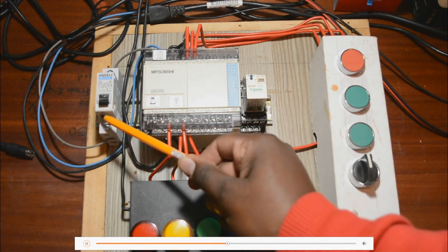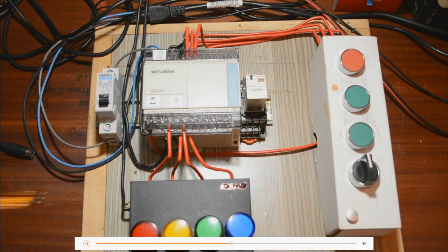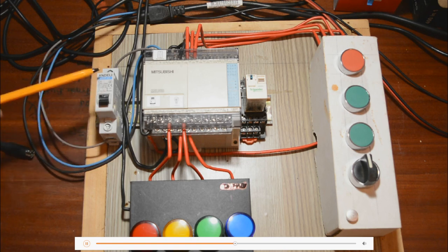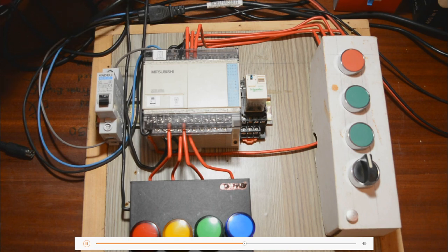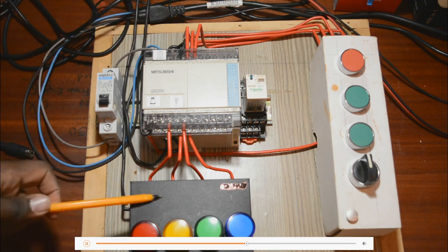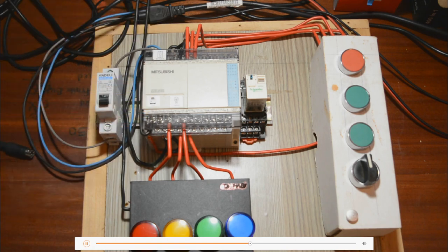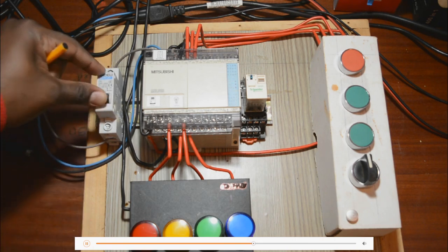Something very important is this circuit breaker here. Always ensure that you have a safe way of turning on and off power for the PLC. You could use a switch, but I thought a circuit breaker would come in more handy and also be a safer way when working with high voltage. Remember, the first topic that we covered was safety, because safety is very important when working with PLCs. So ensure that anywhere you are is safe and any connections you have are very safe. Also, you need to know how to connect your output devices, that is, how they should be powered on.